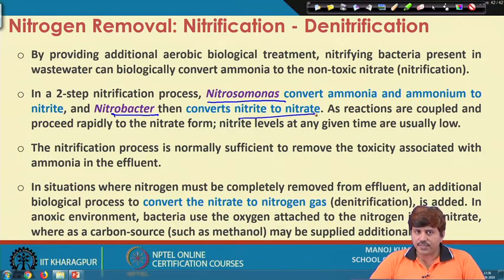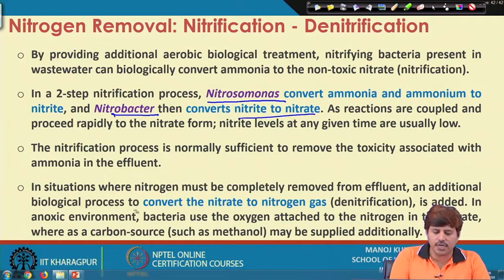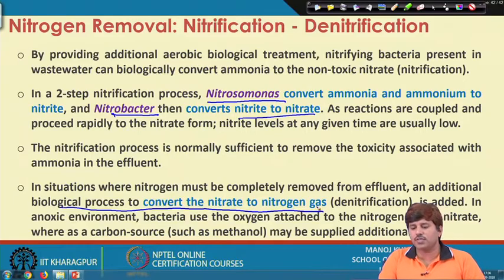However, in cases where we need to remove the nitrogen completely from the system, we must go for an additional biological process which converts nitrate to nitrogen gas, basically referred to as denitrification. This is done in an anoxic, or anaerobic, environment, where there is no free oxygen present in the system.